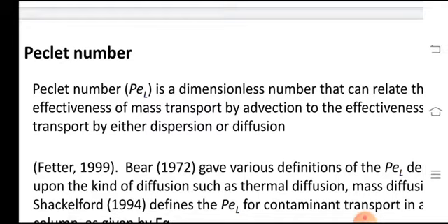parameter to differentiate between the sorption process and desorption process. Now how will we define it? We will develop a relationship between the advection process and the diffusion process. So what was the advection process? It is the change in mass transfer through the flow, through the velocity, and through the advection process, and it is involving the Darcy velocity through which the water is moving.